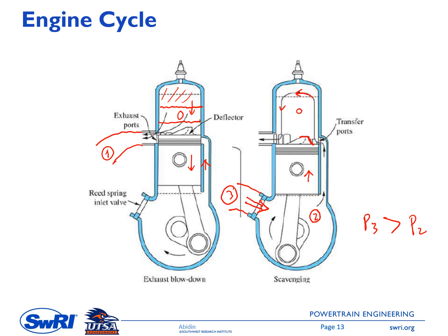In 4-stroke, you will have 4 strokes for sure. You will have 2 crank rotations for one complete cycle. In 2-stroke engine, you will have only 1 crank rotation. So from the power density perspective, this 2-stroke engine will have much higher power density, but it won't be double, okay, it won't be double. Why? Because of this poor scavenging performance.